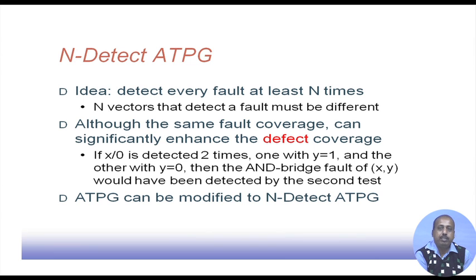Also, there may be some other points, like suppose we want to generate a test pattern set which consumes less power. In that case, possibly we can generate a redundant set of test patterns where every fault is detected by many patterns and then try to do a pick and choose. While doing this, we pick up those vectors where the coverage is high, at the same time the power consumption will be low.